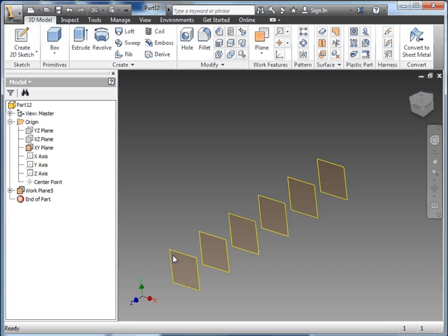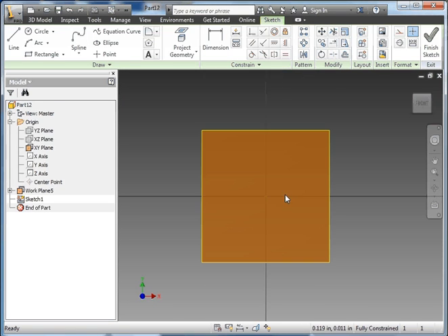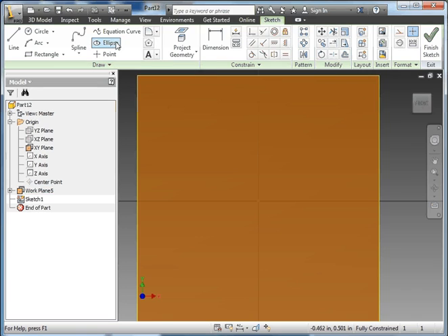The next thing we need to do is start sketching the different cuts of the toothbrush. So we're going to go create 2D sketch on that first plane, and we're just going to draw a small circle using the end point, and we'll do about a 1/4 inch. There we go. So that's going to be the end of our toothbrush. Finish sketch.